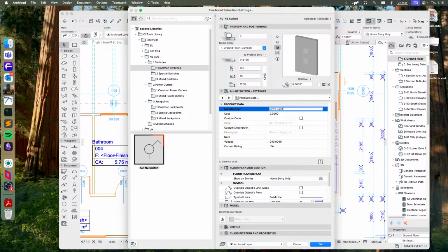And you can probably also see that as I move this, it is chunking the movement in 15-degree pieces, so it won't just swing around to any value and give you some wild angle that you need to somehow reproduce. It is locked to 15 degree chunks. You can change that if you need to, but by default it will do this. So it means that you can more easily sort of freehand these without having to worry about getting bizarre angles showing up there. So we can draw that on.